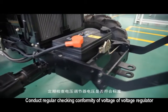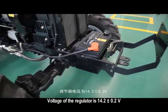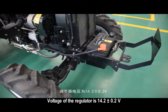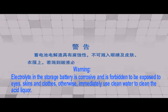Conduct regular checking conformity of voltage regulator. Voltage of the regulator is 14.2±0.2 volt. Warning: electrolyte in the storage battery is corrosive and is forbidden to be exposed to eyes, skins and clothes. Otherwise, immediately use clean water to clean the acid liquor.